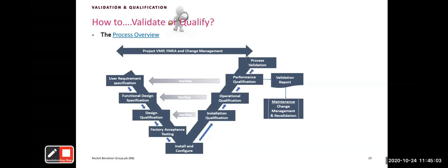At the end of the exercise, going through all your operational checks, which includes safety checks. So you want to check that your machine guarding is effective. They will tell you, put on the equipment. The moment you open the door, the equipment shuts down, and you have maybe a red light blinking somewhere, or you have an audio response somewhere. That's the safety check during operation. So you do all those checks, and you confirm whether they responded as expected or not in your protocol. And that's you taking results, and you're generating documented evidence that proves that this equipment is performing as expected. So that's what you do during operation.